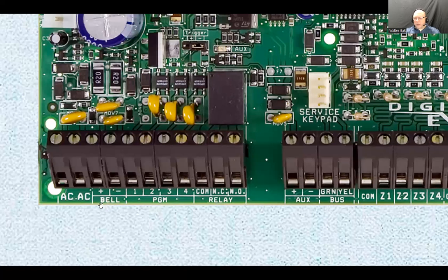This one here says bell, plus and minus. It is for the siren. A bell is a siren. In the old days there used to be mechanical bells, so I guess that terminology has transferred into today's times. So that is basically a siren. That is going to produce 12 volts DC, and the siren looks like a paging horn for the most part, and sometimes they're just square boxes that mount on the wall or in the ceiling. Once that thing receives 12 volts DC, it is going to go, well, what some people would call crazy. The tone that it produces and the volume it produces that tone with is supposed to work on human ears and brain so that you just don't want to be in there.